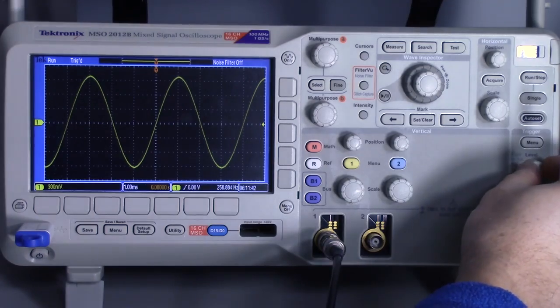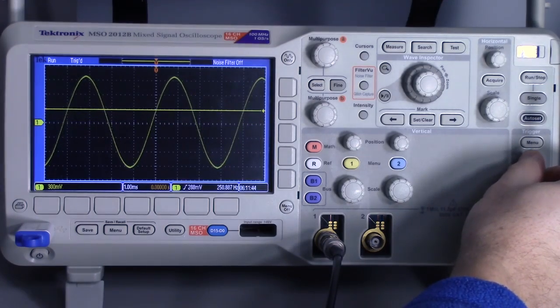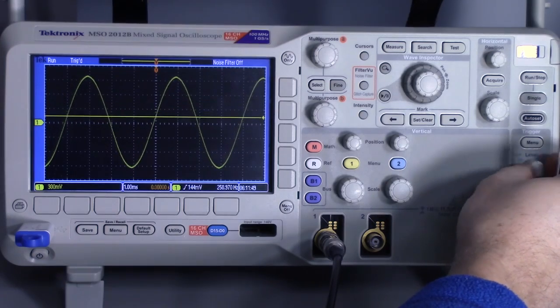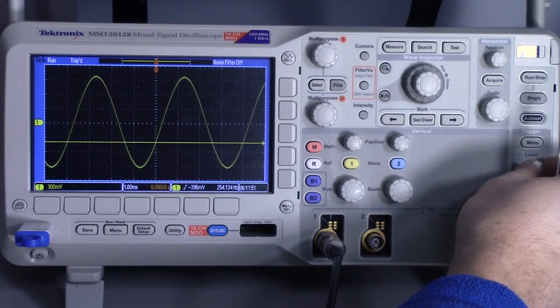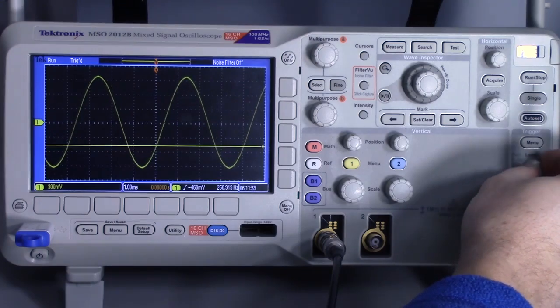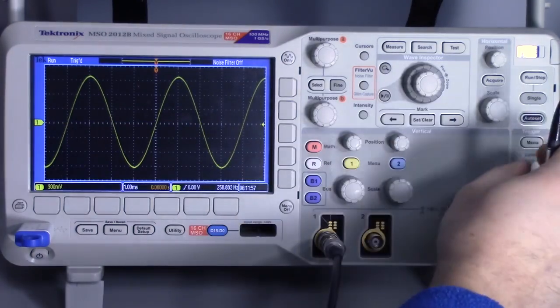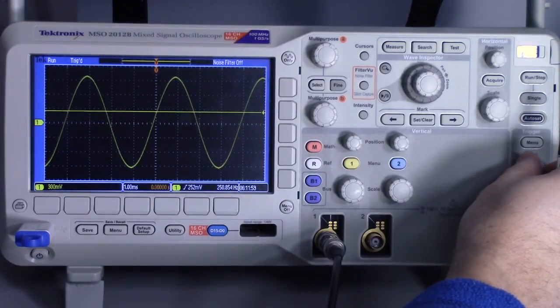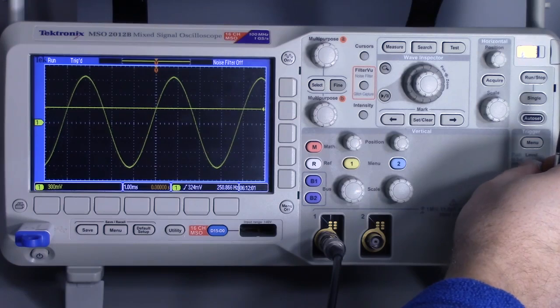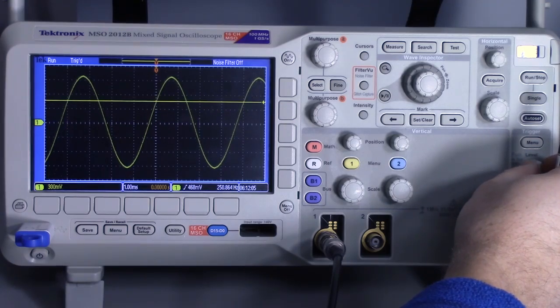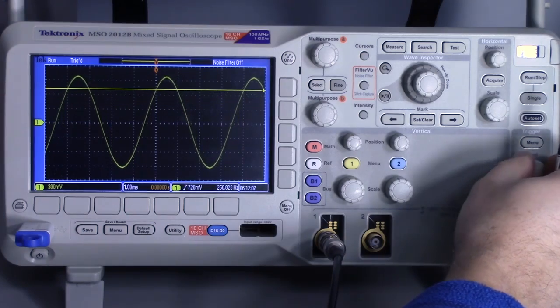All we need to do is adjust that, and you can see a yellow horizontal line appears. It seems like I'm moving the waveform back and forth, but what I'm doing is setting the trigger level. You can also look down here that it will change. So I can set it to a specific voltage. Since it's 300 millivolts per division, it's going to be a little math. It's going to be funny.